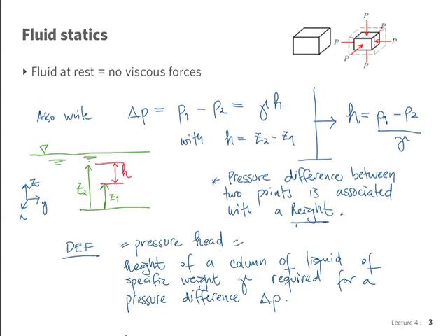It just is. So what you need to be careful about is that even though we're really talking about pressure, the dimensions of head are length because it's a height. It's just that it's the height of a column of liquid which is equivalent to a pressure difference. And it's by a certain tradition in engineering that it has become common usage, and so you need to be aware. Okay?